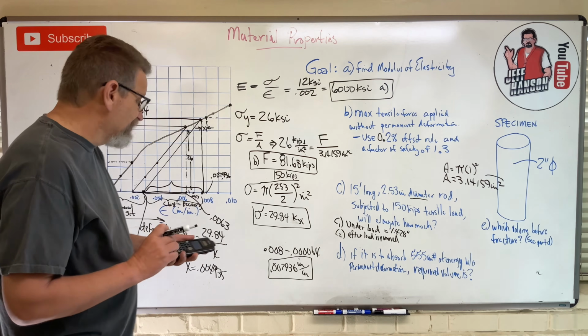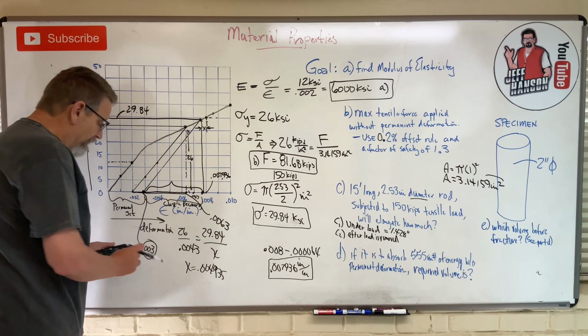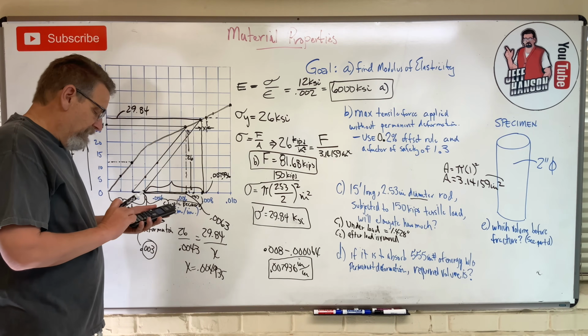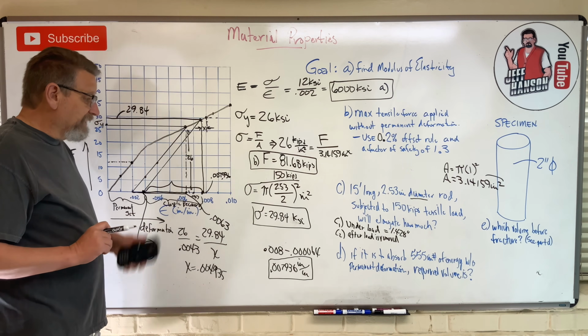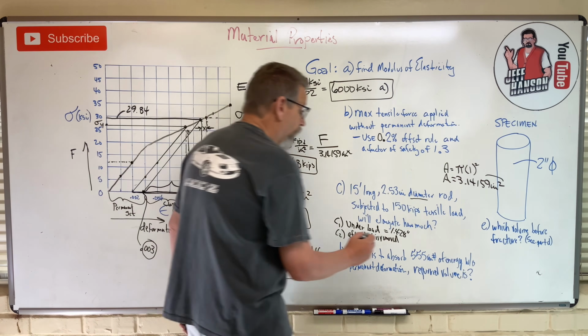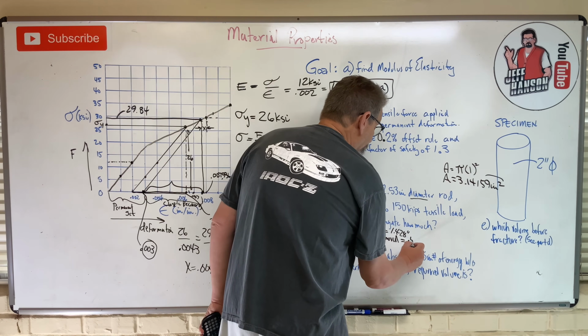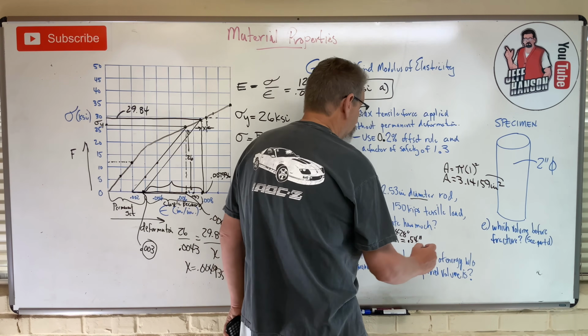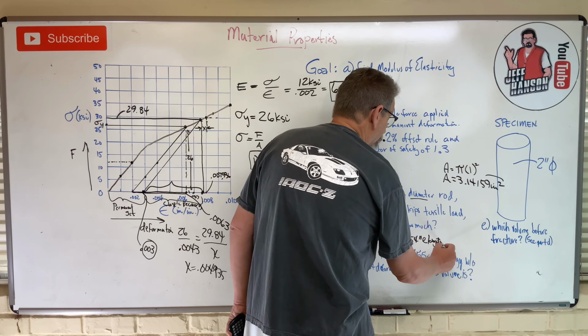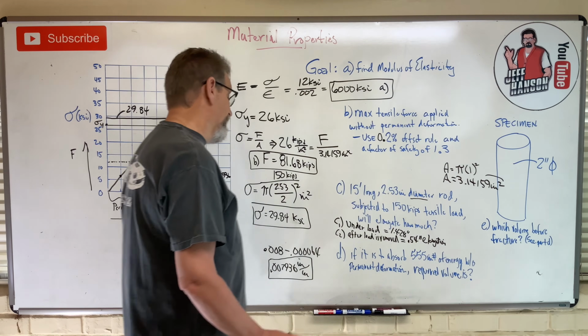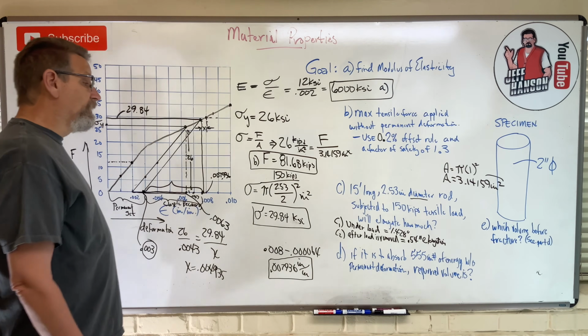It's 180 inches, and then every inch of that is expanded permanently times 0.003. So I get 0.54 inches. So once I take the load off of it, I have a 0.54 inch elongation. Forever and ever.